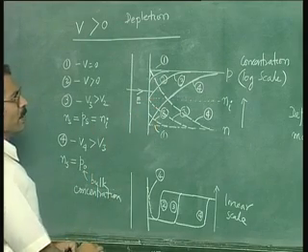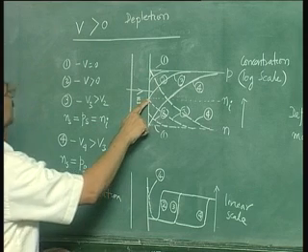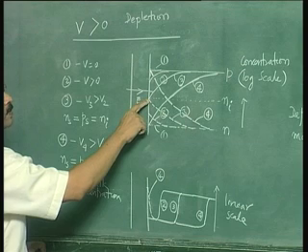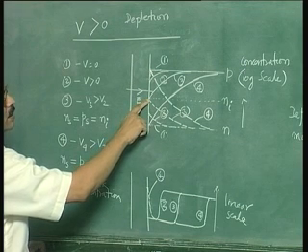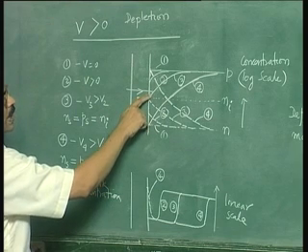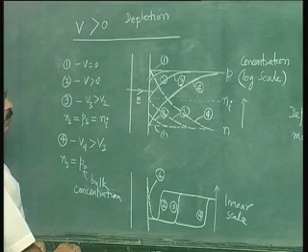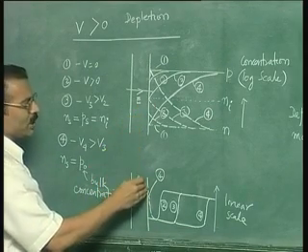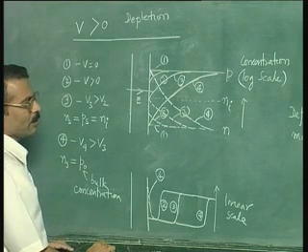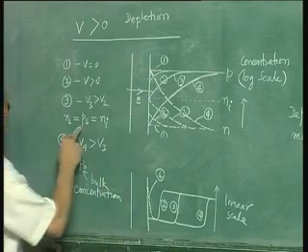Now, strictly speaking, inversion starts occurring beyond this condition, that is V3, because beyond this condition your surface concentration of electrons will be more than the surface concentration of holes. However, since you are not able to see much of an electron charge at the interface, normally one talks about inversion occurring only beyond a voltage V4.